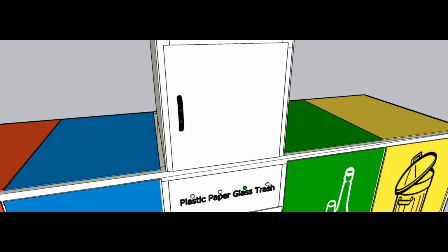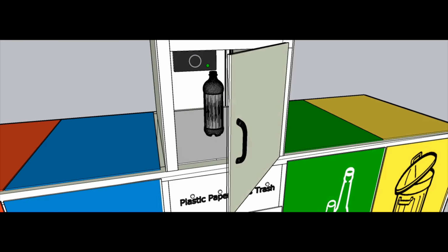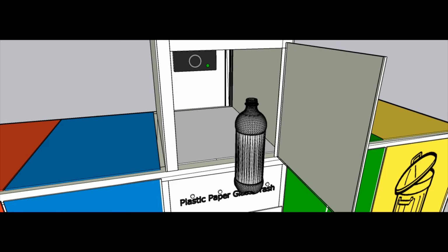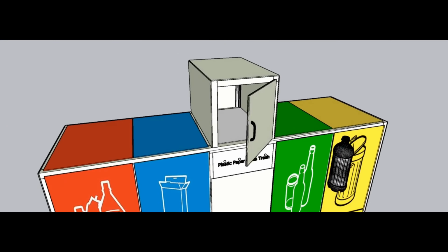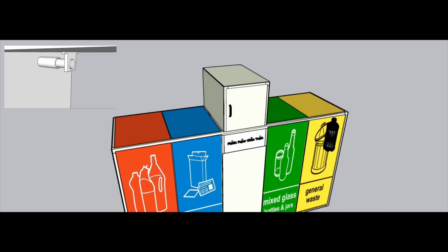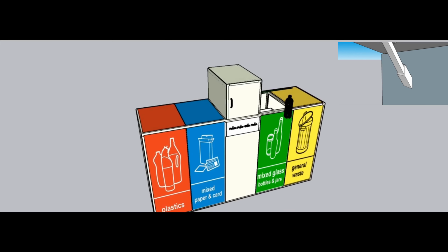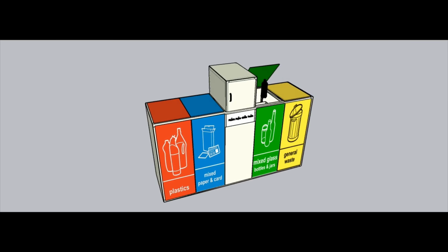Now that the recyclable has been identified, an LED on the front of the machine turns green, signifying which bin the recyclable belongs to. In this case, it is glass. The user can now remove the recyclable from the center compartment. A solenoid is now energized and unlocks the lid to the correct bin, which initiates a linear actuator to open the lid for the user automatically. Thus, the user can now dispose of the bottle properly. This process can be explained by the following circuit simulation.